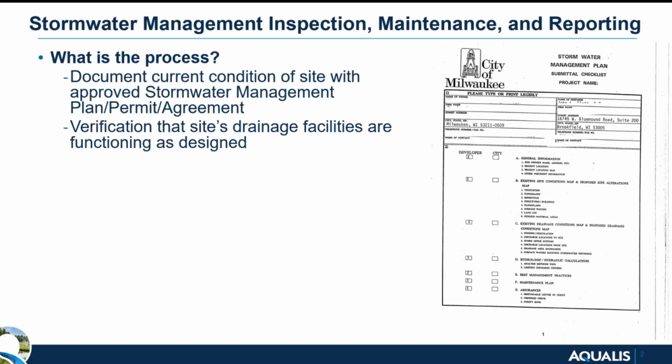In green infrastructure, we're going to be looking at what's out there for vegetation versus the original planting and vegetation plan. We might be looking at infiltration rates if we're talking about a permeable system or a biofiltration system. And then for green or gray infrastructure as well, we're checking capacity and conveyance. We just want to make sure that as the design was approved, that is the way that the device is currently functioning.